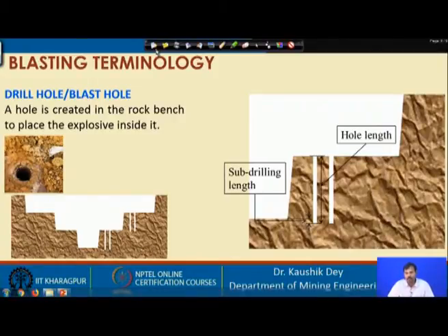You can ask why we need sub drilling. When we cover the explosive rock interaction, it will be easier to understand that sub drilling is essential for bench blasting. As we are going for some additional drilling, it is better to get fragmentation of the whole rock mass, so that no rock portion is left at this position.